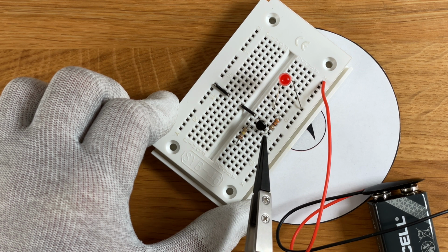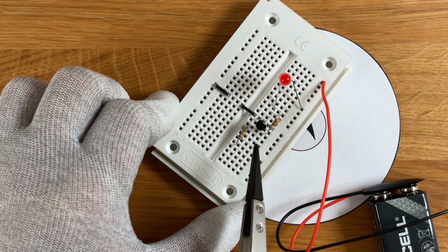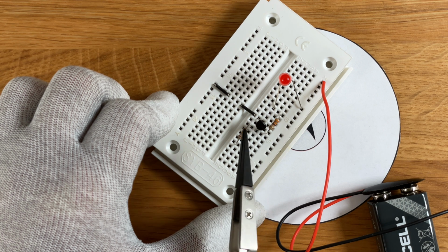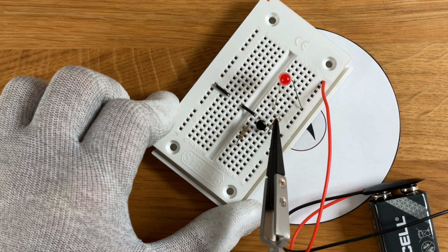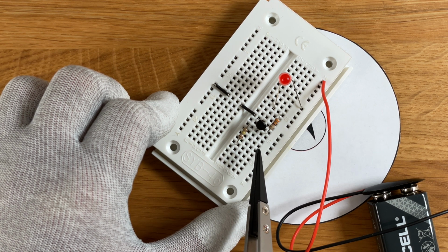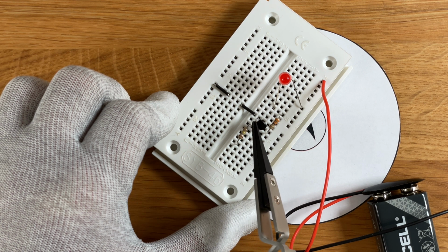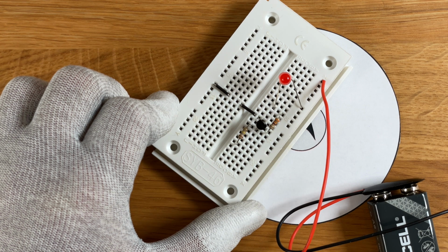Then the transistor, as we designed it to be, is operating in its saturation mode, which means the connection between collector and emitter is ideally conductive regarding the parameters of this transistor. And this means we have a current of approximately 20 milliamps flowing through the collector-emitter path, through the resistor here, through the LED, and into the terminal of the battery.